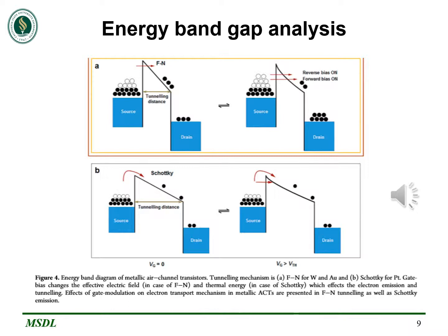Furthermore, under the influence of gate voltage, the energy level bends slightly downward, controlling barrier width and enabling a few electrons to tunnel through at a lower energy level, as shown in figure B. Therefore, we observe Fowler-Nordheim tunneling when the gate voltage is different from 0 for platinum. However, the bending effect is not significant due to the higher work function and electrode gap, and hence the dominant mechanism remains Schottky in all the cases for platinum.